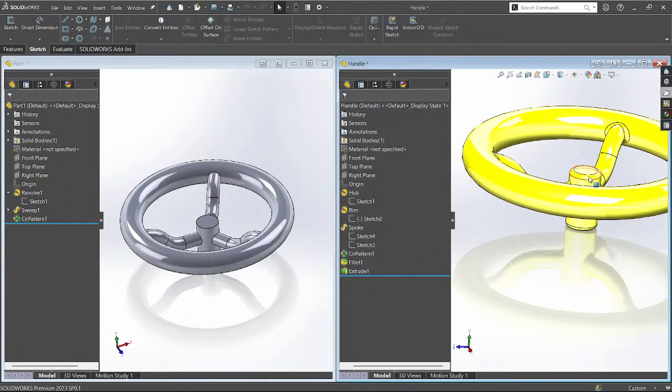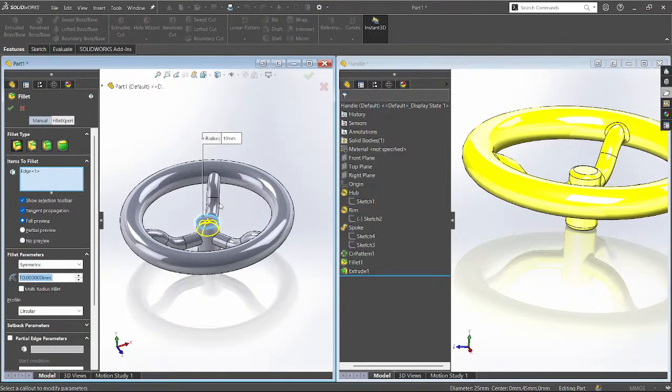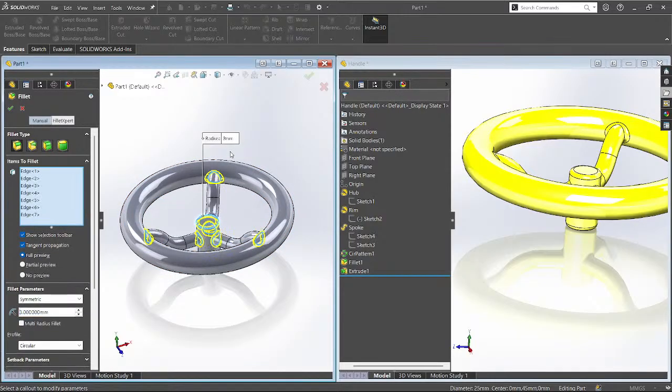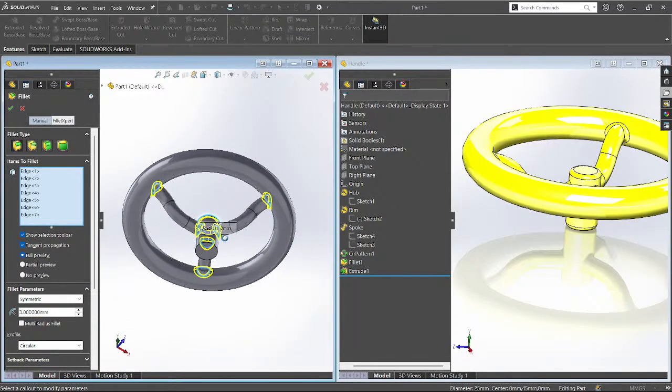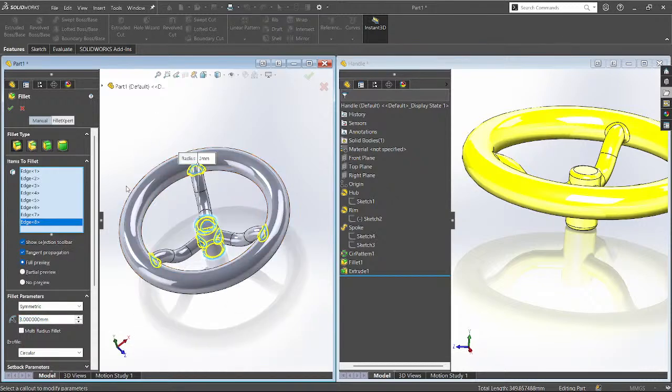That is applying the chamfer or fillet, the radius is 3 here. Here also it is 3, everywhere it is 3. What I can do is simply select this edge and assign the radius 3 here and also here. You can just switch. I would like to have these all, right? And even this one, green check.